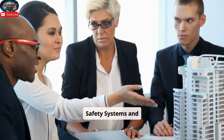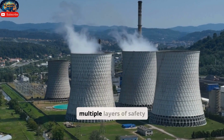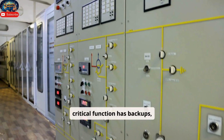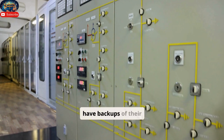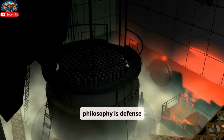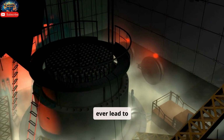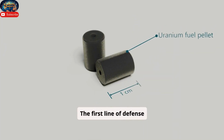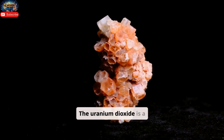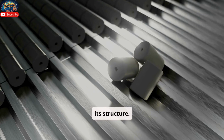Safety systems and redundancy. Nuclear power plants are designed with multiple layers of safety systems. Every critical function has backups, and many of those backups have backups of their own. The guiding philosophy is defense in depth. No single failure should ever lead to danger. The first line of defense is the fuel pellet itself. The uranium dioxide is a ceramic material that holds most fission products within its structure.